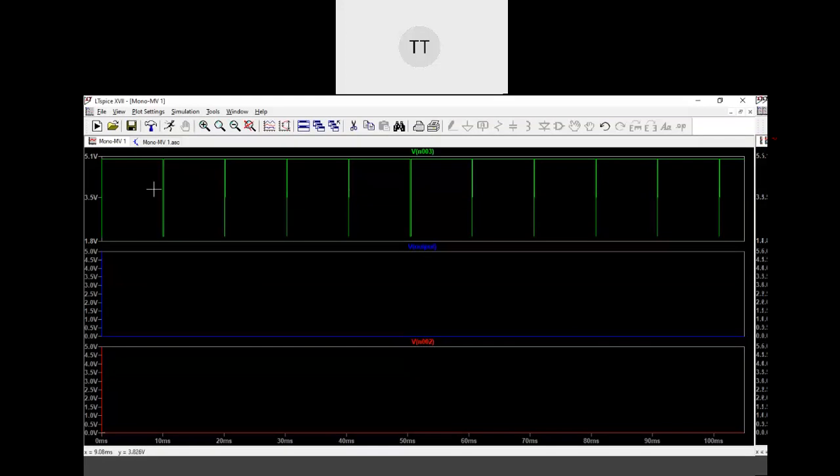If you carefully see, can you see there is a trigger signal coming here now also? Yes, but it is not going below VTL, not going below 1.5 volt. Can you see the output voltage is always 0? Correct? And the capacitor is not at all charging.